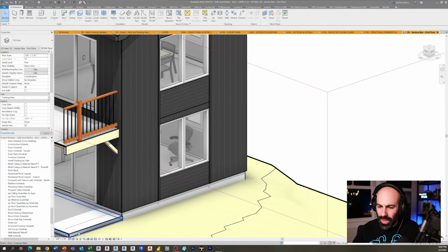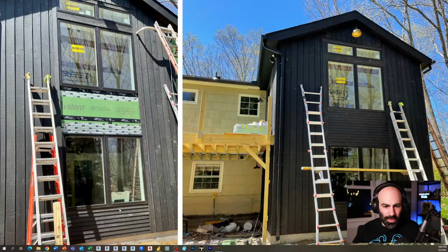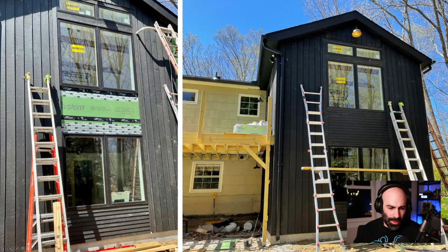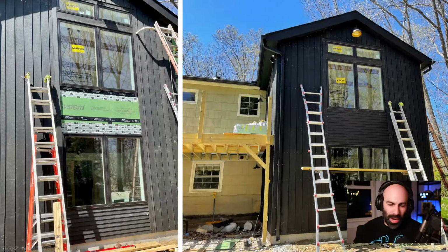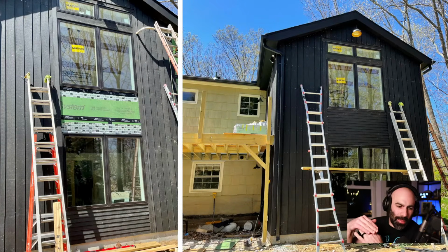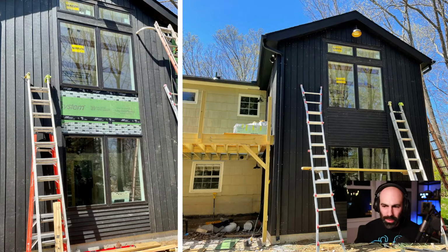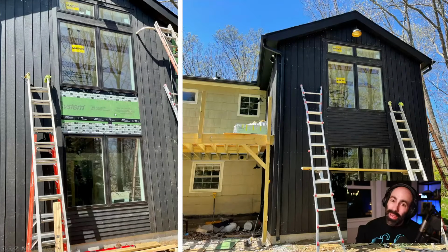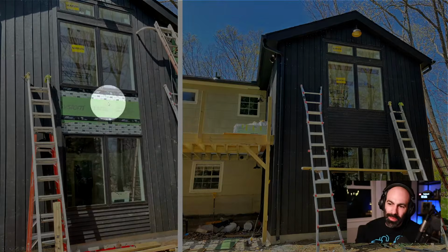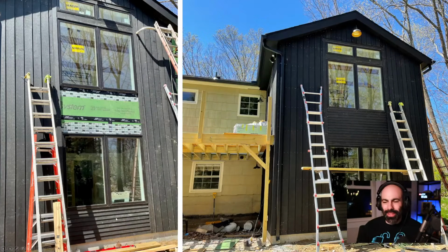But the one thing that I screwed up on is not anticipating, when I took the area off, how those overlaps affected it and how I was tightening them up. So if you look closely here, what I ended up doing was these were 6-inch beveled cedar siding, but I overlapped them. I only wanted about 3 inches to go, and so when I did the takeoff, I was using the area. I was putting a little factor in there, but I just didn't figure that 3-inch overlap. So I ended up getting to the point where I was like halfway in here, and I didn't have enough material. And at that point in time, we're in May. And so I probably paid as much for the remaining material as I did for all of the material for the siding, and I had to go get it. I had to stain it, cut it, all that good stuff.